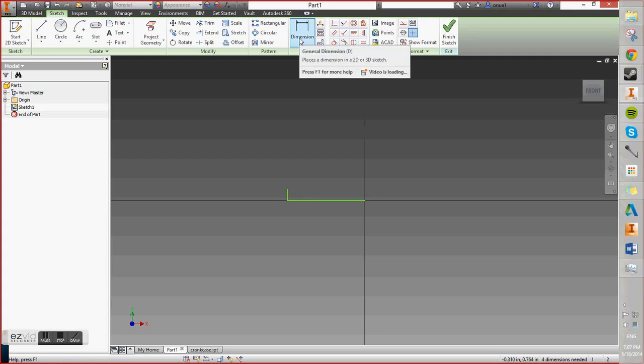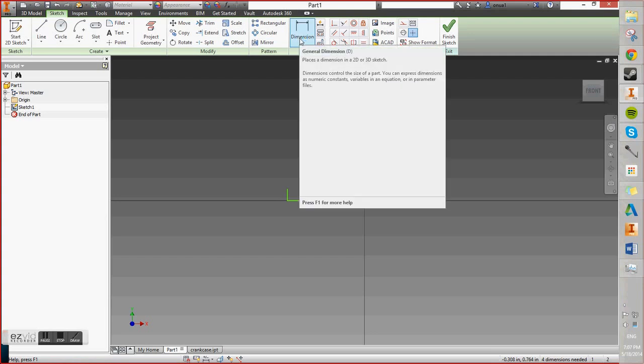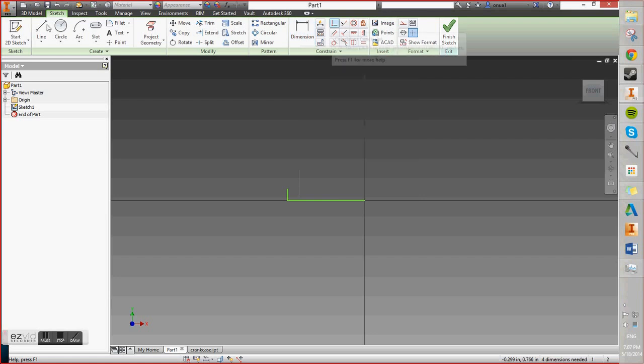And now, if we want to set dimensions, you can dimension it there. But before we dimension it, let's set up a center line. So we're going to click the little center line button and mark this as the center of our piece. Center lines help with dimensions in big parts. So we're going to dimension from the endpoint to the center line, and as you notice, it dimensions the whole piece. Since we're going from the center line, as soon as there's a mirror on the other side.